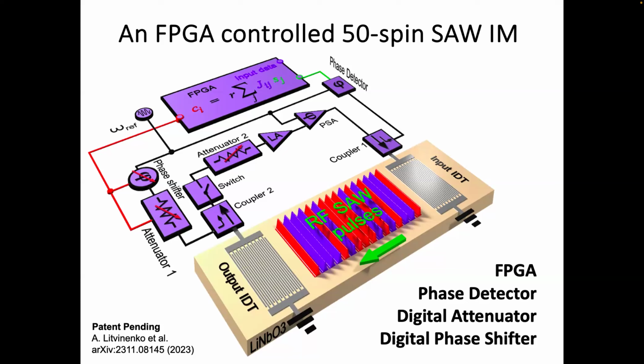And the YIG would then be bonded. That's what we're doing. If we pattern the YIG films into tracks, we would have individual antennas or transducers on the tracks, and that would have to be wire bonded to whatever RF CMOS chip you have. So it's a heterogeneous integration that way. Yeah.